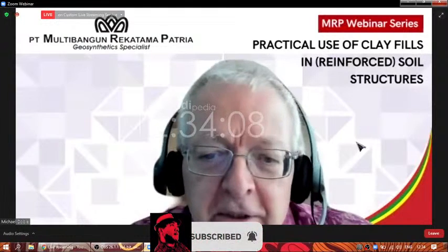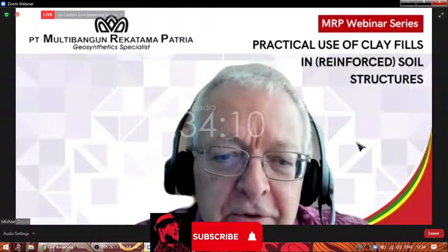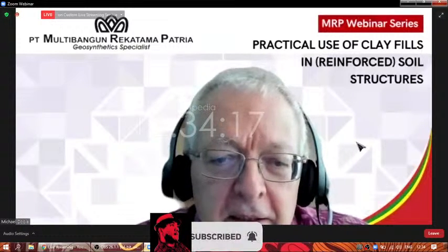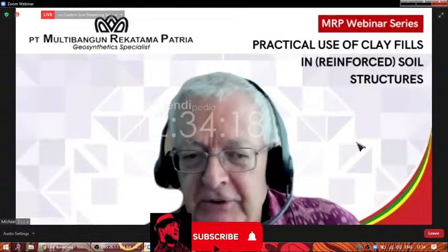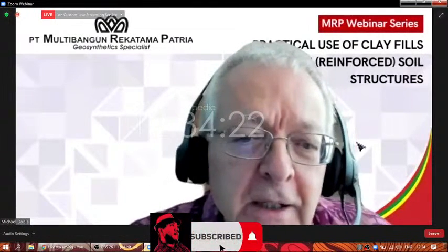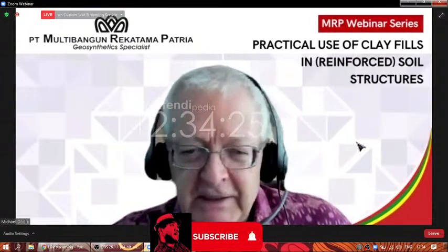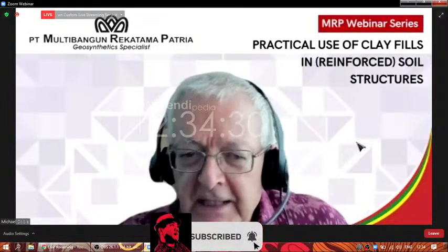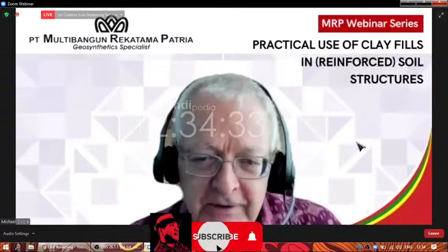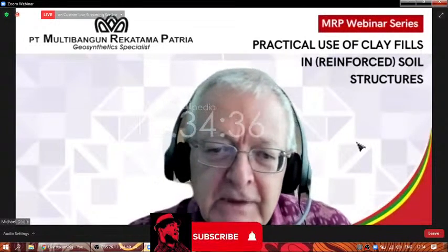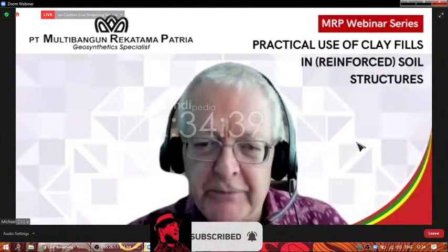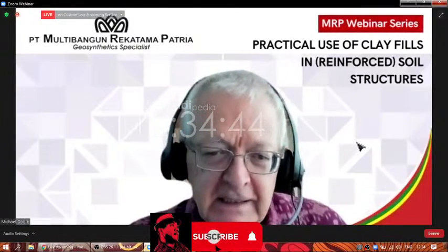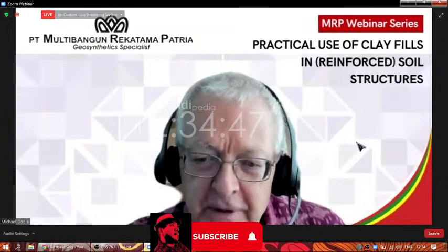Vacuum preloading with vertical drains on soft soils, suction and smear zone, vertical drain. Okay, again, I think this is for another question, Isha, for a different topic. Today was about clay fills and the natural creation of suction in a soil simply by its condition. We don't normally apply vacuum preloading to fills. It's normally only applied to soft foundation soils. So I think, again, that's really a slightly different topic.